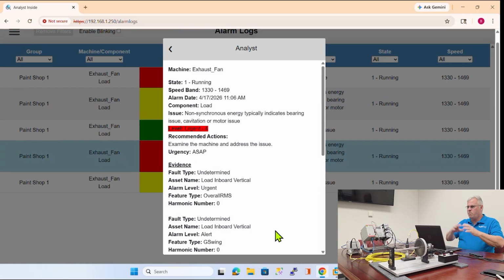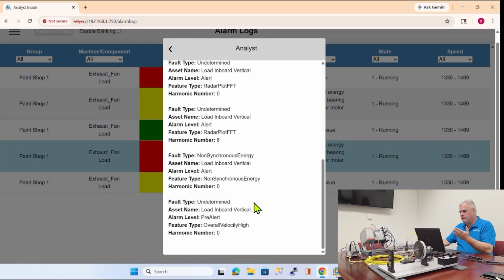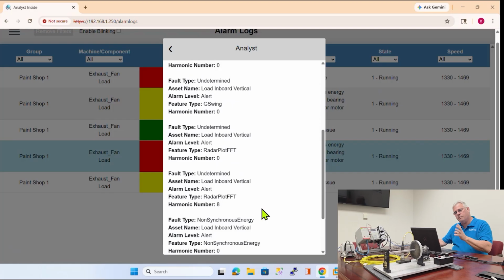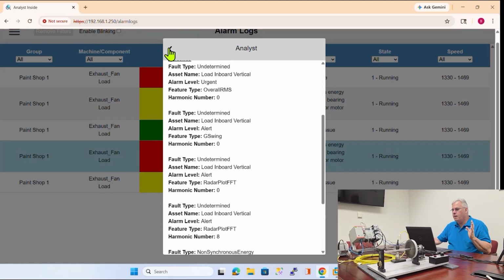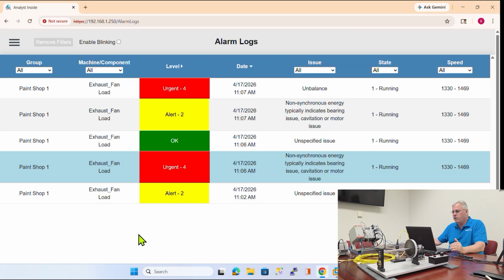There are a whole bunch of techniques out there. I think there are 15 to 20 different techniques that most vibration guys use, and we've done that here. We've seen information in each of these items. That harmonic 8, all of this information means something to the vibe guy. So what we've done is have this thing transition through and create alarms and alerts.